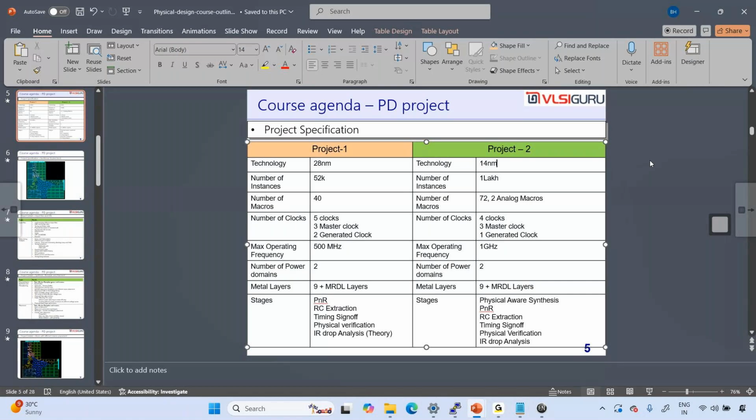Physical design cannot be done blindly, right? We require input files for physical design. That should be given from the foundry. For 5 nm, I require files from the foundry, right? Then I should get files from TSMC. I will get files from TSMC only if I pay in crores, only if I get my IC fabricated there. I cannot get that. So we will get only files which are given from Synopsys.